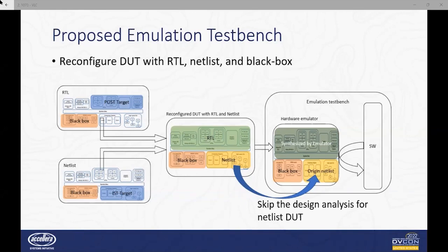The emulator supports probing the RTL signal during runtime without any compilation. It was very useful to merge and debug list sequence during real usage verification. We could verify the system operation mode over all expected BIST operation at the pre-silicon verification phase.